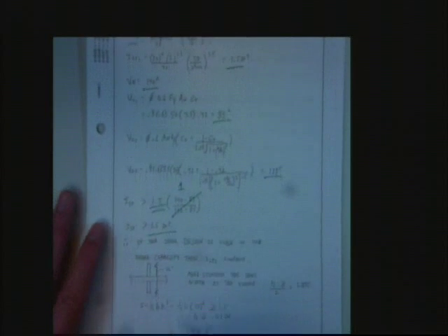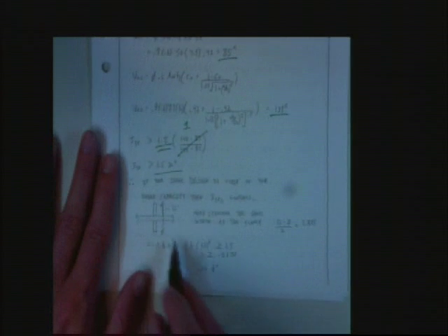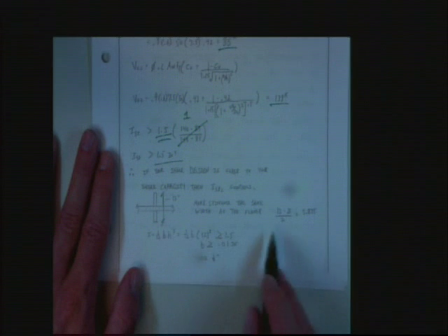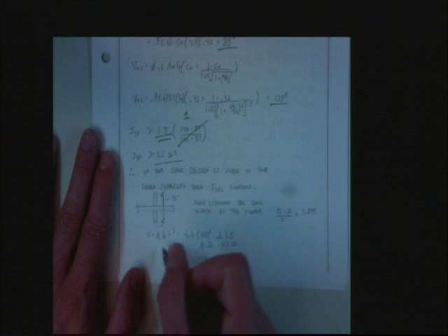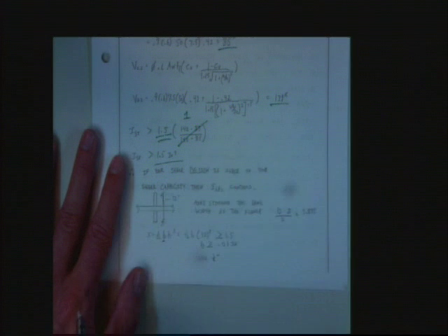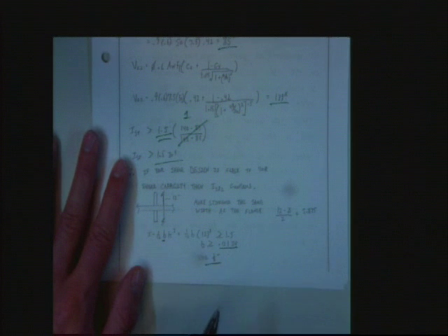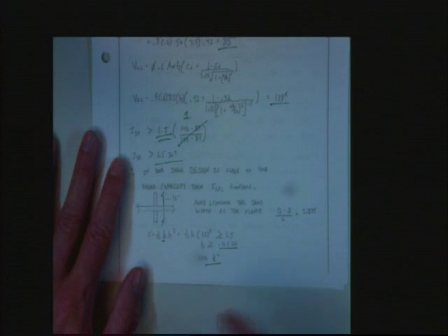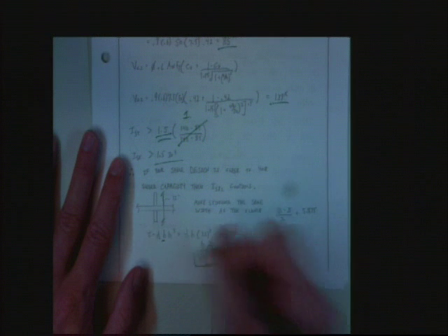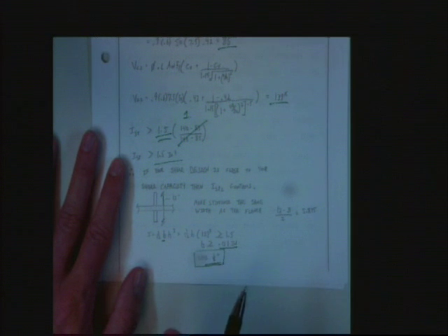But actually, none of this tells you anything about height. We'll go ahead and calculate the thickness that we need of the stiffener, and it's like 0.01 inches, which is like a joke, right? So you can get away with an eighth, whatever your minimum size is to put your weld on. Does that make sense? What we'll find coming up is that the stiffener size isn't that big of a deal. It's all about the welds. How many welds are there? How long are they? That's what's going to cost a lot of money.